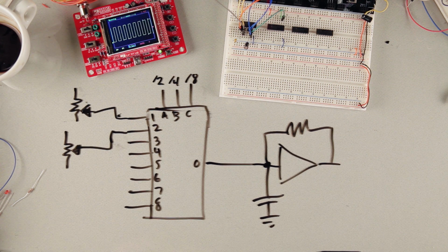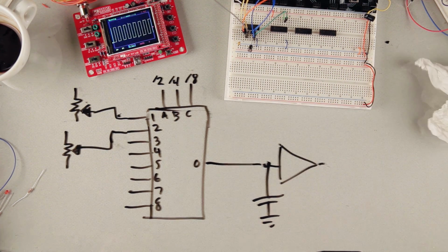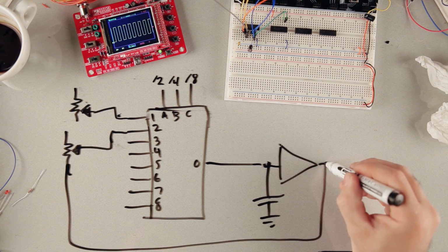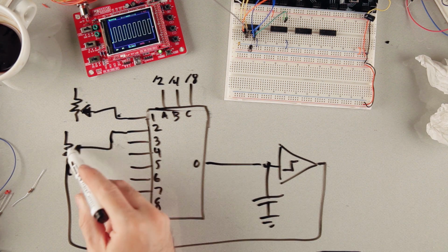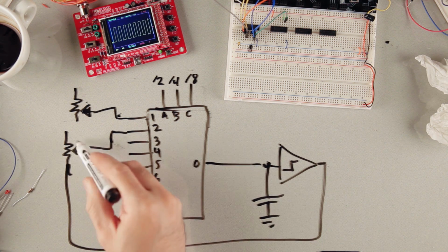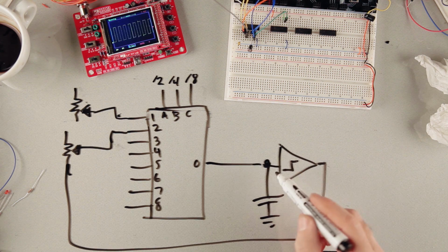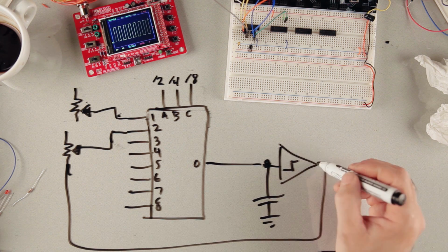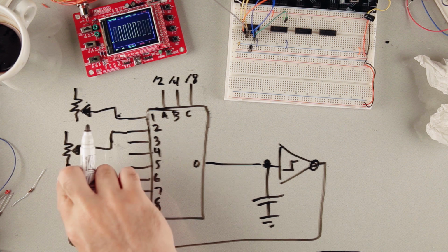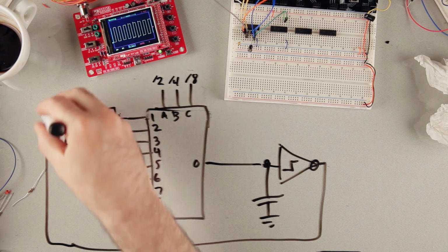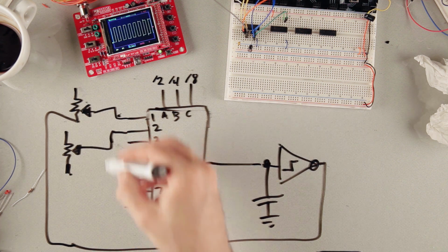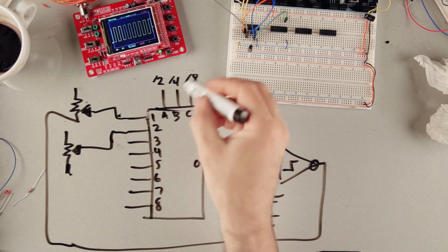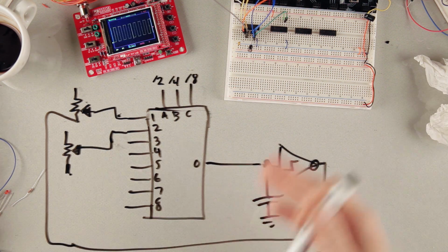And basically, what we're actually going to be doing is we're going to be feeding that back. So when channel 2 is selected, it's making a feedback path through this potentiometer, and that's going to set the pitch of this. And then when channel 1 is selected, it will be feeding that back through, and so on. So for each of these steps, we're going to be able to choose a different pitch. And then we can sequence through and choose the different pitches.